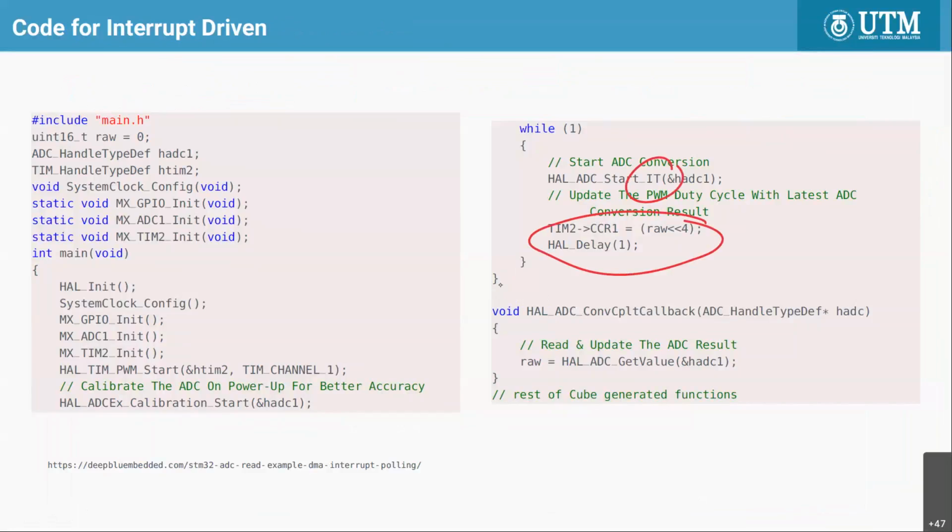You can do whatever you like with the data, but you must provide a callback function, and in the callback function you get the data from the handle. You must provide the callback function to read the data. Because this is HAL, you don't actually read the register. You read the data from the structure.